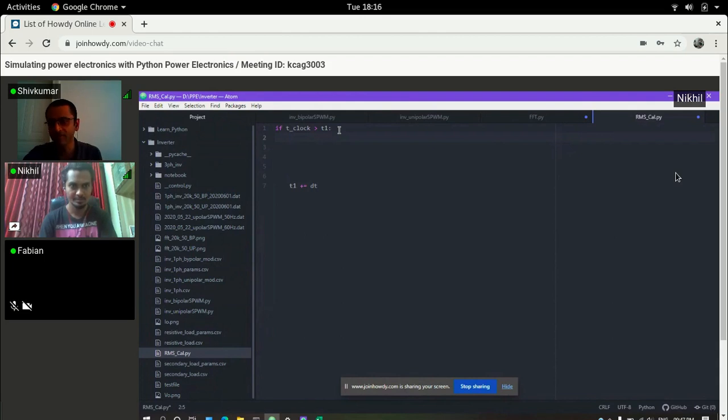See, this is not a control file. Control file means you are running control at fixed times, even signal processing. This is a computational file. So you want to run it as many times as possible, right? So make dt the same as your simulation time. You can go up and put dt is equal to 1 microsecond, if 1 microsecond is the simulation time. Before the if statement, yeah. So these are defined at the head.